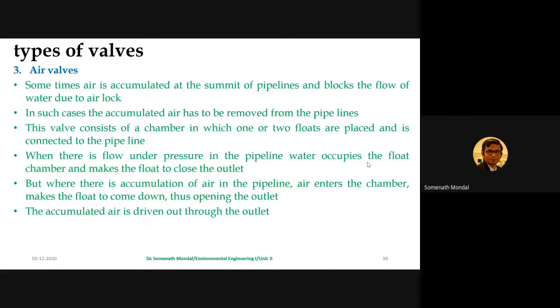If there is a sudden stop in the water flow, and after a certain point of time, even if your tank is full, water is not coming in the tap, this happens because of the air choking or air lock in the water pipeline.